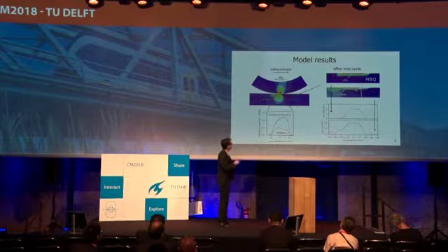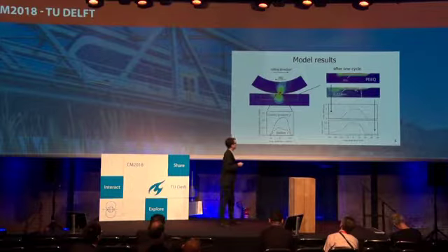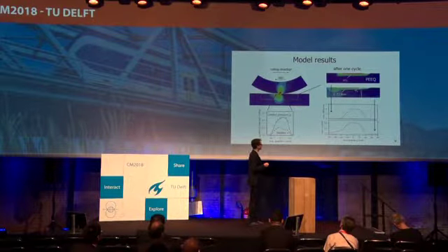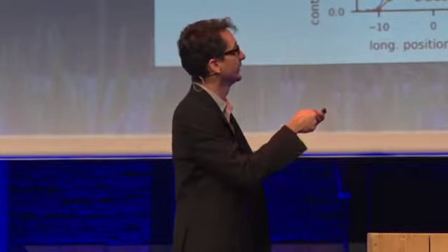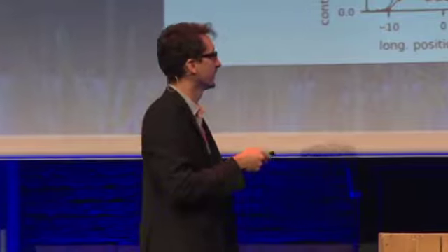And to compare different curves like that, or different results like that, we extract curves. And those curves mean that we look at each cross-section along the longitudinal direction and take the maximum value to see how uniform it is. We see here it's quite uniform. We also see it here in this diagram. The same for the displacement in longitudinal direction. This is not that uniform.